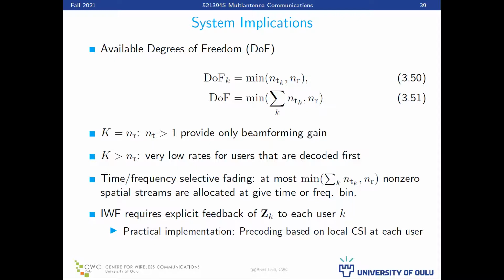In the extreme case, there's only 1 user which is active in 1 subcarrier, because you can use that power budget more efficiently in other subcarriers. In the extreme case, each user would be transmitting in 1 subcarrier only, right? If you think about the water filling, that's what would happen. But the solution would be orthogonal.